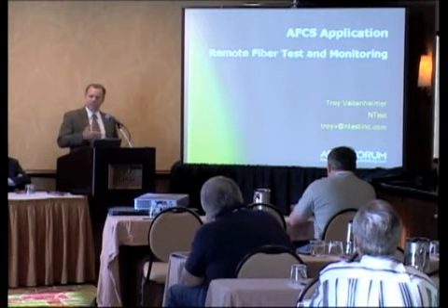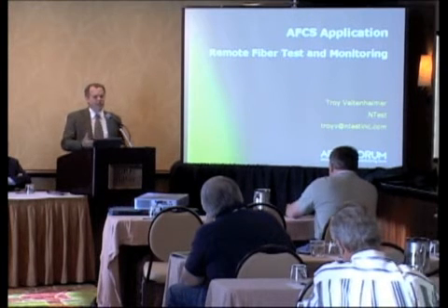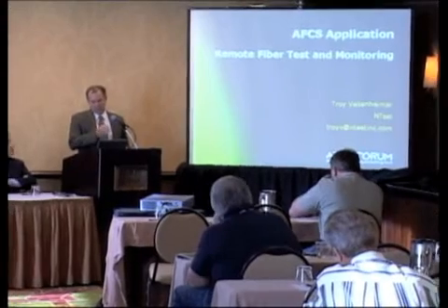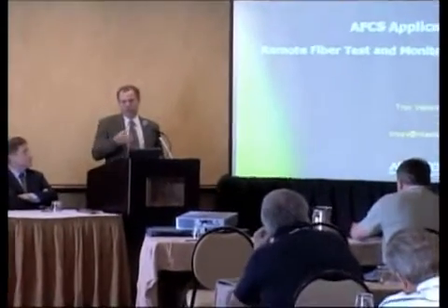And then it continually, through the use of the OTDR, the software, and the switches in the system, will switch fiber to fiber to fiber, round robin. It'll take the physical characteristics of the latest trace and compare it to the reference trace. And if there's a deviation at that point, then there'll be an alarm at the NOC, and the alarm will be sent to all the appropriate people that are responsible for taking care of a problem like that.